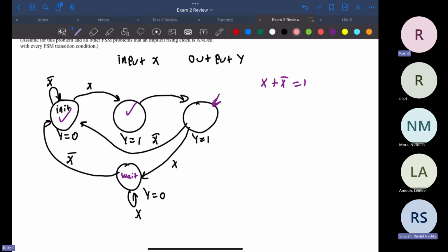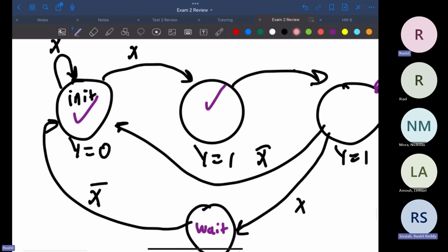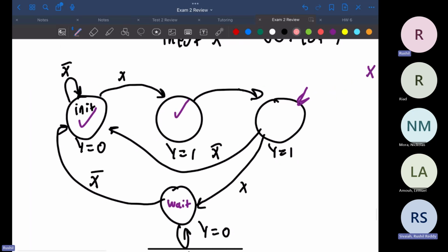But we have to label our state. This will make it easier whenever you're actually making a truth table. So we do this in binary, of course, since we have 4 states. How many binary values do you need for 4 states? 2. I accidentally gave away the answer while I was talking, but we'll have 00, 01, 10, and 11. I chose those values. You can choose whatever you could possibly want as your state values. Just never repeat them.